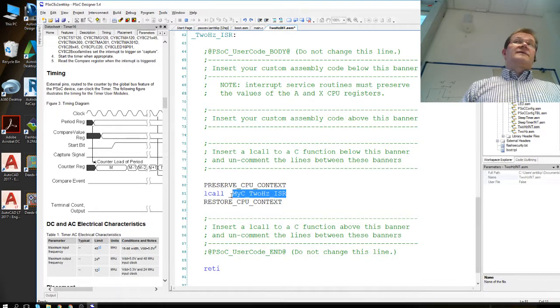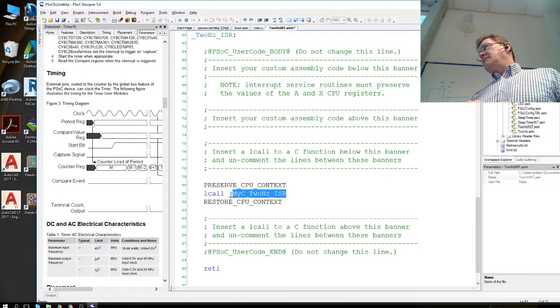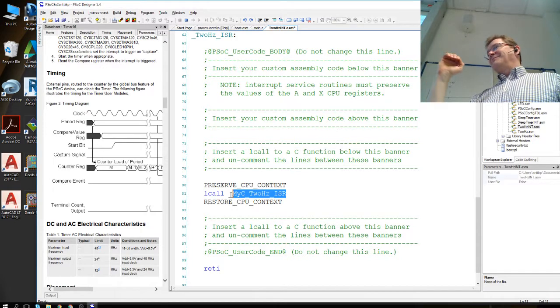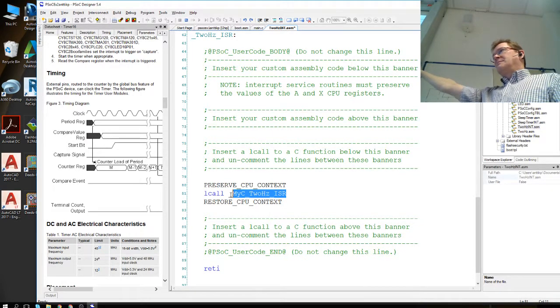I copied it without the first underscore, since the C compiler compiles kind of semi-assembly code where all the variable mnemonics and all the C variables and function names have the underscore in the beginning. Okay, that makes it easy to actually call any C routine from assembly.